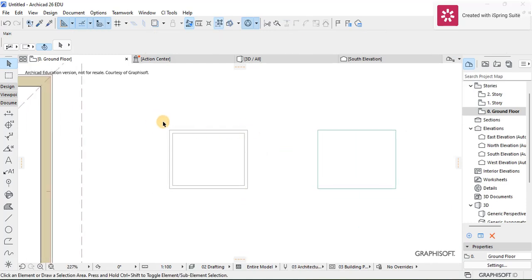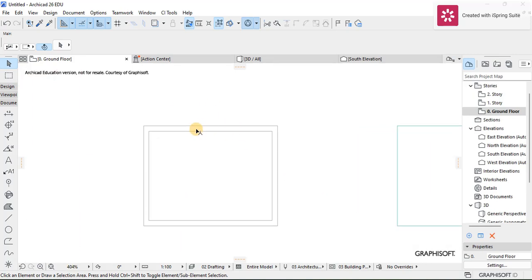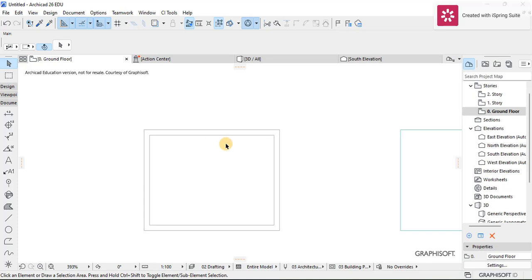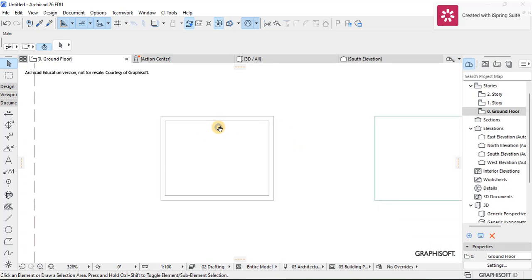I've first copied the first outline, and then I pasted it in the same location, and then I chose one of the copies, then I offset it down by this 80 millimeters here, so you can have a window outline here.